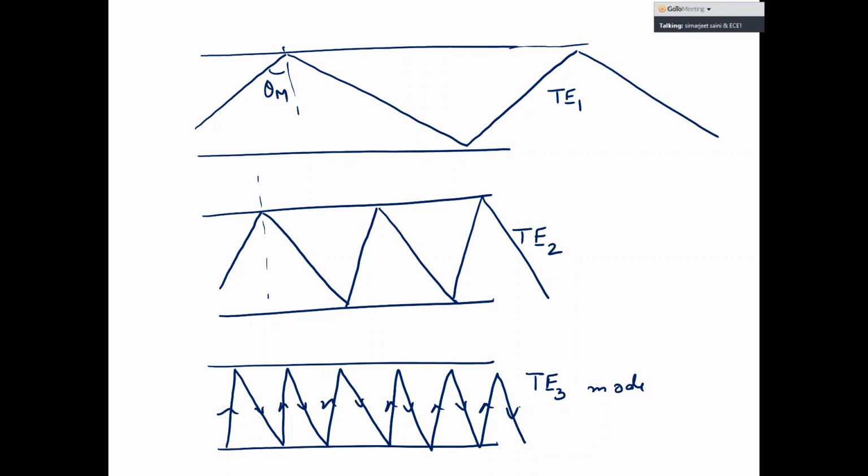However, this is effectively the reason why we start seeing discretized modes. If you notice when I was showing you the modes of the TE, it looked like a guitar string. The first order mode was such that the electric field has to be zero at the boundaries, and then there is a single hump. That's the first order mode of a guitar string. Why does the mode of a guitar string happen? Because you get reflections, two reflections, right at the places where you're holding the guitar string. And only certain distributions are allowed after that. There is a superposition of those two reflections, constructive or destructive, and only certain distributions would be allowed.